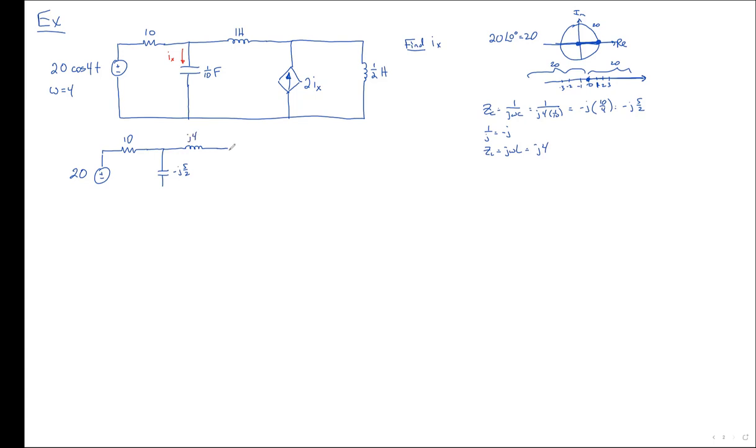Yeah. All right. Can't forget where this current is. We're going to draw it as a capital I sub x now, since it's like a DC value. We're in the frequency domain. And this thing has a really easy transform. Instead of 2 times little i sub x, it's 2 times capital I sub x. And we already know how to figure out the impedance of an inductor. It's j omega L. Omega is 4, as Kyle said. So this is just going to be j2.